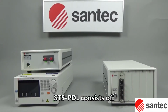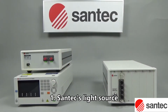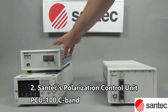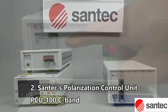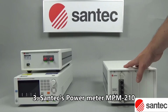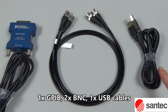Let's have a look at the STS test system for PDL measurement. It consists of Santec's light source in O, C, L or S band. Here we are going to use the TSL-550 SCL band model, Santec's polarization control unit, or PCU-100, in the corresponding optical band, either O band or C band. Here we are using the C band model. And finally, Santec's optical power meter MPM-210. These instruments communicate between themselves and with your PC through GPIB, BNC, and USB cables.